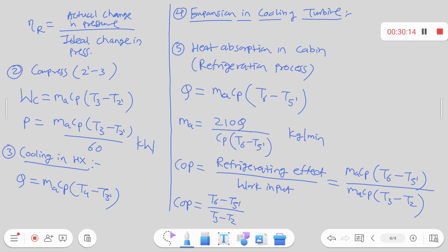Right? Our target is to calculate. They may ask mass flow rate required. They may ask COP. They may ask work of compressor. If they ask COP or mass of air required, then in that case the compressor work needs to be calculated. Temperature and pressure at each stage need to be calculated. Right? For that, the temperature pressure relationship will be used. Understood all of you? Right?